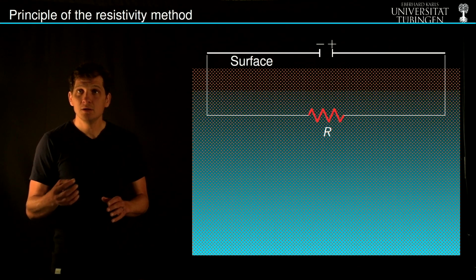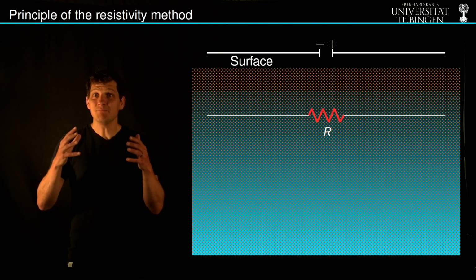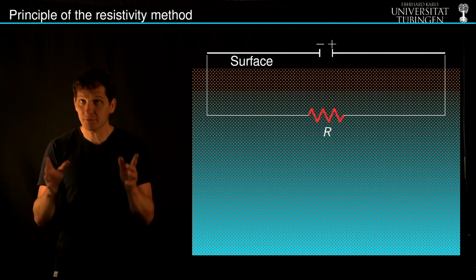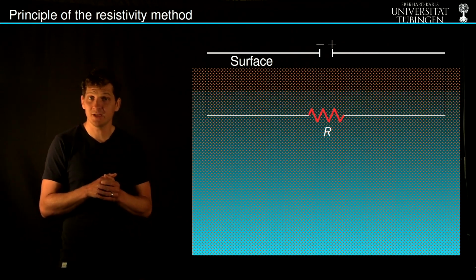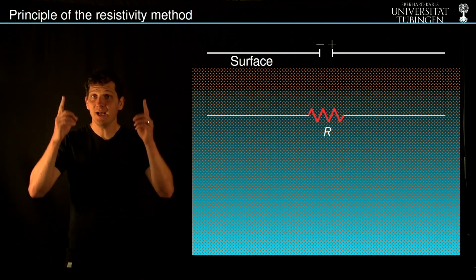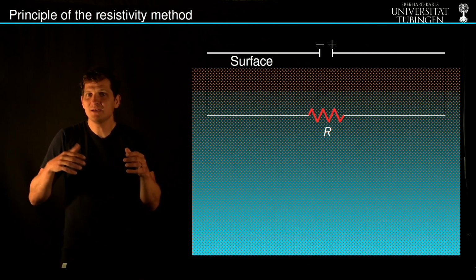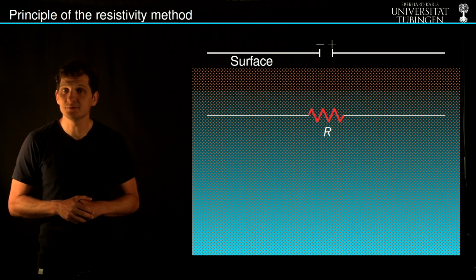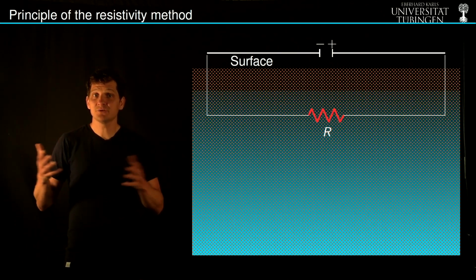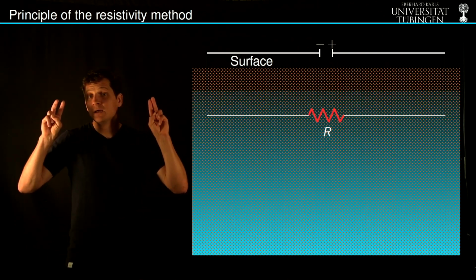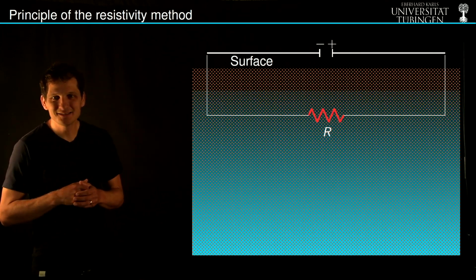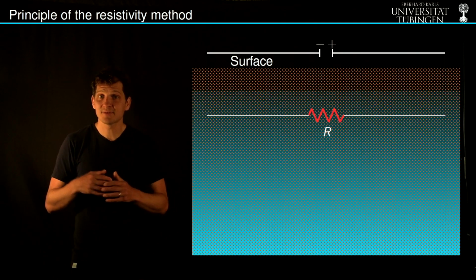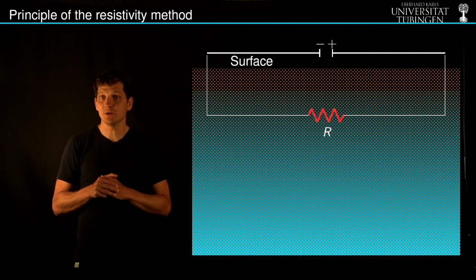The principle of the resistivity method can be compared to the simplest electrical circuit, which contains a battery as a source for an electrical potential. It contains electrodes, meaning essentially metal sticks where we inject the current into the subsurface. And then the electrical circle is closed with cables, which in our case corresponds to some yet to be determined flow path of the electrical current through the soil.